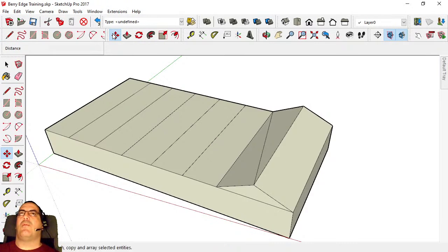So we'll put our tool back into move tool mode. We will click on that line. Oh, hang on. What have we got there? Hit escape. If you go to move something and the thing that you hoped to select didn't move or something else moved, hit escape, and if you did make any modifications, Control Z will undo them. So escape, Control Z are always your emergency get out of jail free card.